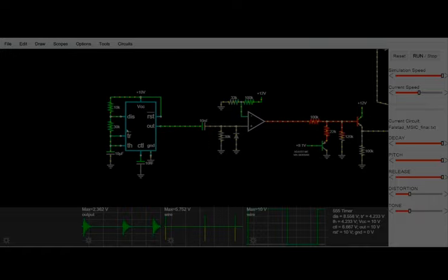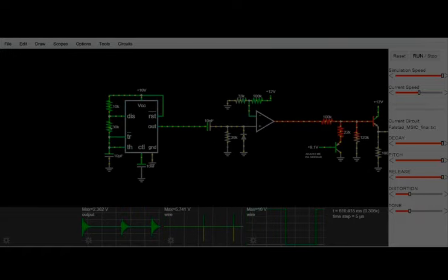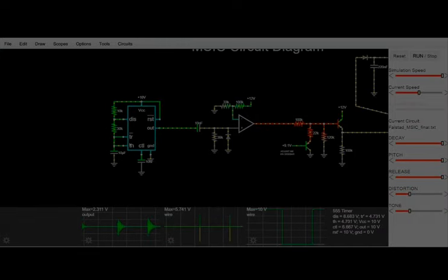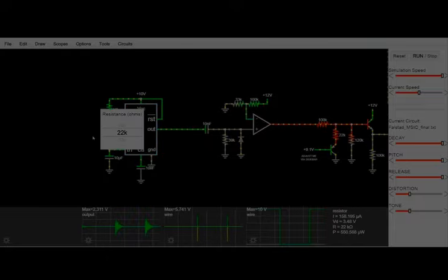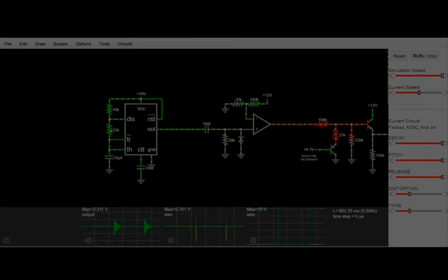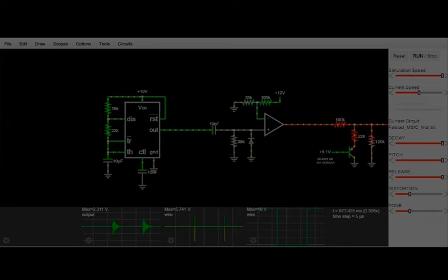So here, instead of using a potentiometer, I've just used a resistor and it gives out a fixed frequency. But in the breadboard implementation, we have also used a potentiometer in series with this, so that we can vary the frequency as per our requirement.